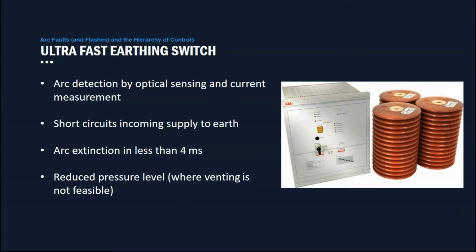The ultra-fast earthing switch. What we do here is sense the onset of an arc fault and introduce a short circuit to earth. These devices are proprietary devices. They're generally quite expensive, tens of thousands of dollars a time. I could tell a little story about a team of testing engineers who wondered if they worked, and so exercised them, and yes, they do in fact work. Then they had to order some more, much to the chagrin of the project manager.